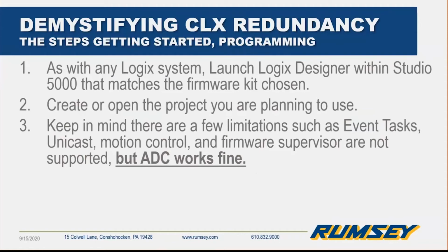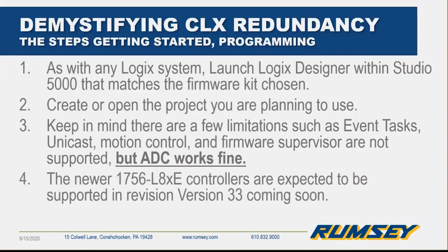You can also do 1756 IO, remotely chassis, add them hot, and all of that, just like you can in the single mode setup for ControlLogix. Now, we're really excited about this. The L8s, I mentioned earlier on some slides, will be supported in version 33. We're expecting this literally any week. It could be this week. I honestly didn't check this morning. I meant to. But version 33 is going to support the L8.